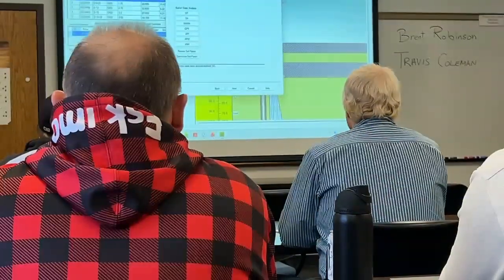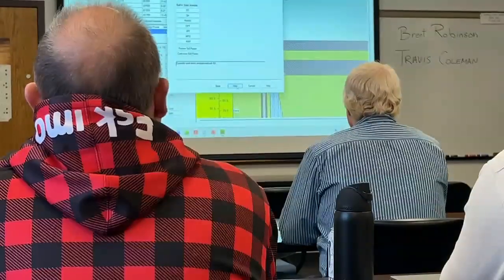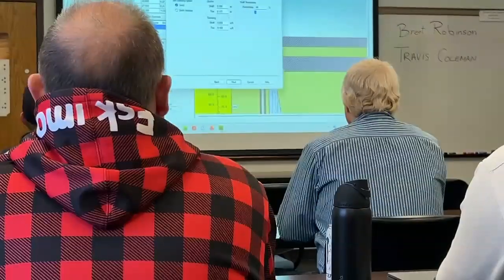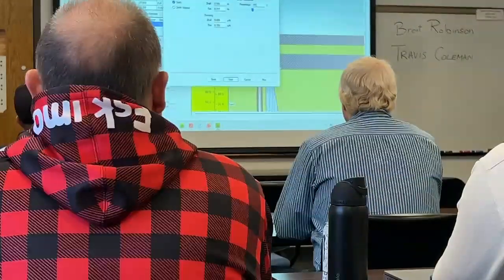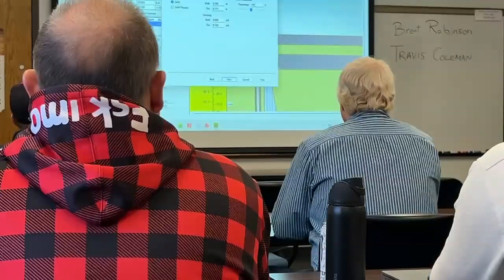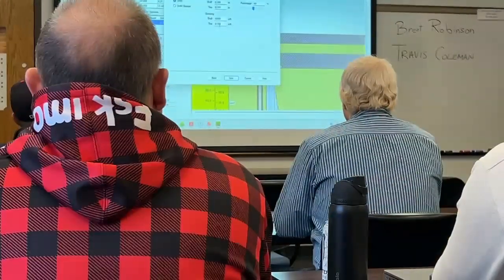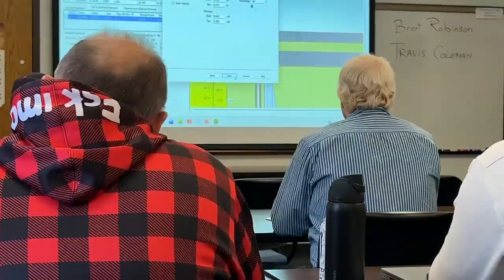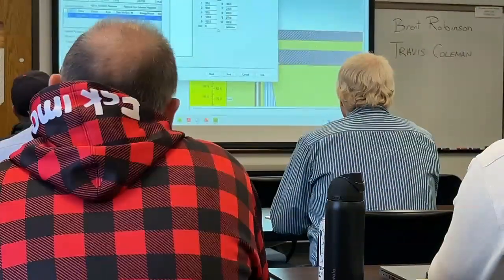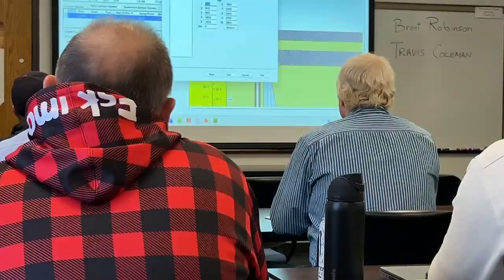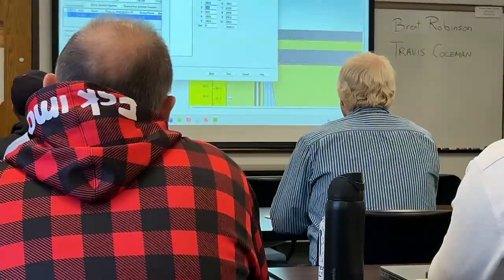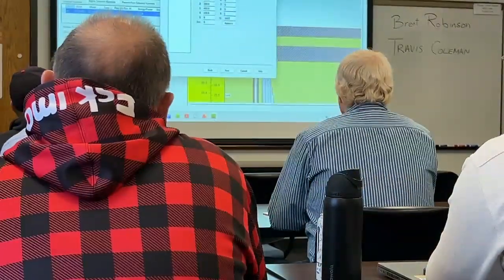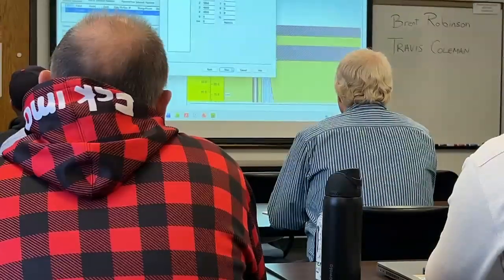So I have taken all the recommended values for these soil types, and it's given me my quick summary right here. So 44% of that capacity is coming on in friction. Those are the damping and quakes it's given me based on the soil types, as well as the size of the pile at the toe. And now I'm going to give it the capacities that I'm interested in analyzing. So I'm just going to enter a few. So we need to achieve 400 kips. So I don't need to look at a big wide range of capacities.